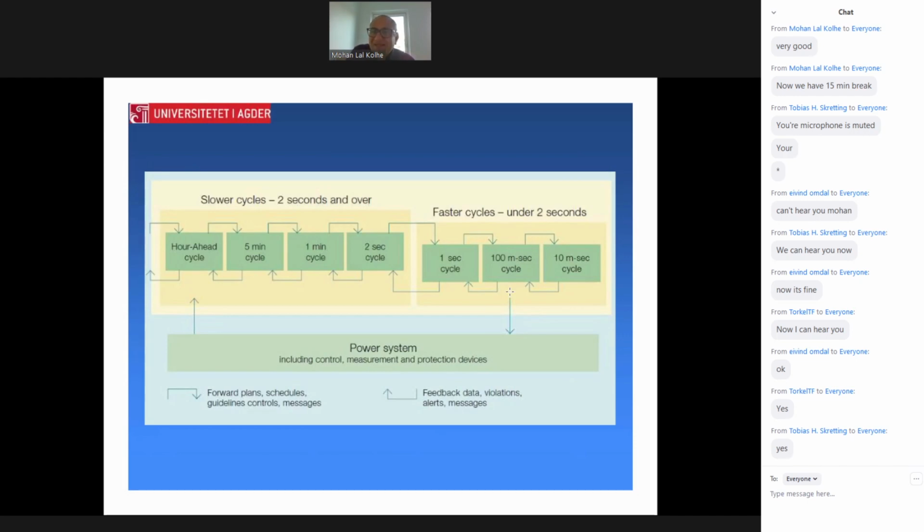The 10 millisecond cycle provides the input to the 100 millisecond cycle at the next level. If that deviation is not fulfilled by the stored kinetic energy of the rotating mass, then another controller or loop has to come into the picture and change how much is required. It then provides a feed-forward input to this cycle or controller also.